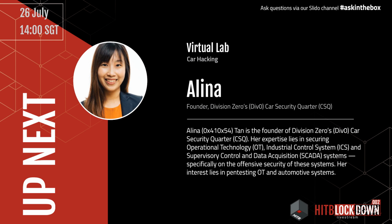So what we did was a man in the middle, tapping into the middle of the traffic of the vehicle. From there, we were able to get the messages out. The interception lies between the cluster meter and the central gateway itself. We tapped from the middle and were able to extract CAN messages.